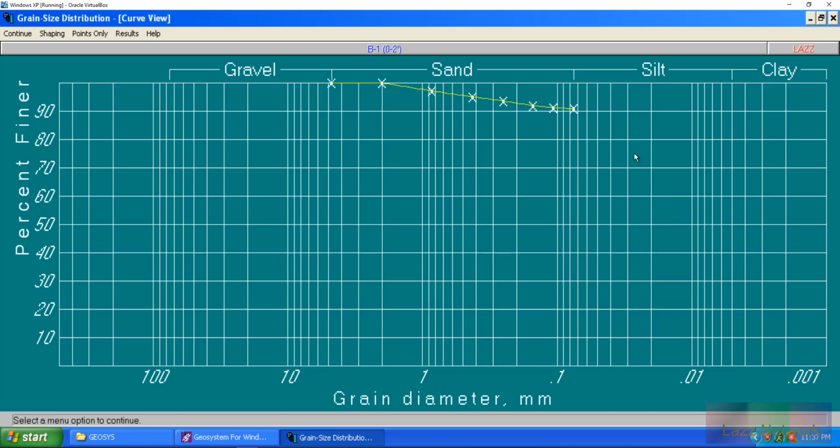And overall, just to explain what a hydrometer is, it mostly just determines what the specific gravity of that material is at that point in time. Technically, where hydrometers get used the most is breweries, places that make alcohol. You can use a hydrometer to tell your alcohol content because of the specific gravity of the beer or the ale, the alcohol itself. Because technically, water itself,